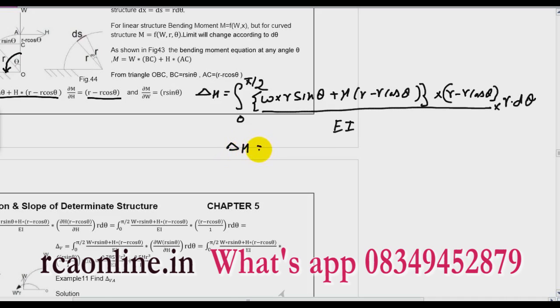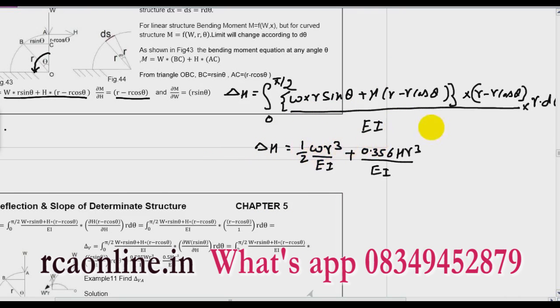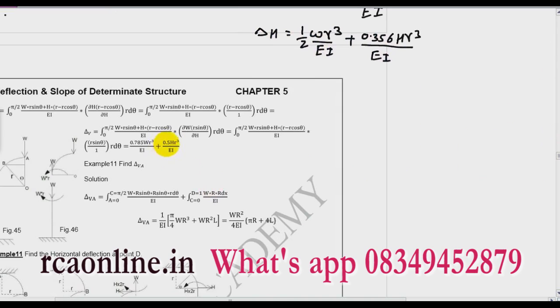Delta H equals, if you solve this, you will get 0.5 WR cube over EI plus 0.356 HR cube over EI. This is the way to solve the curved member. For the horizontal member, as I told you just now, if you solve, you will get 0.785 WR cube over EI plus 0.5 HR cube over EI.